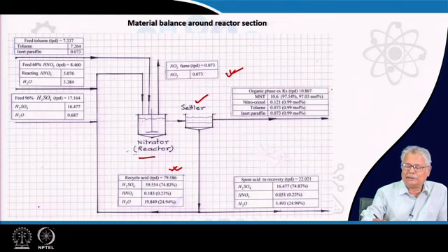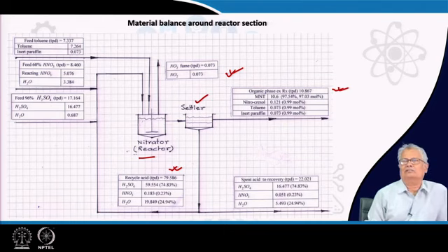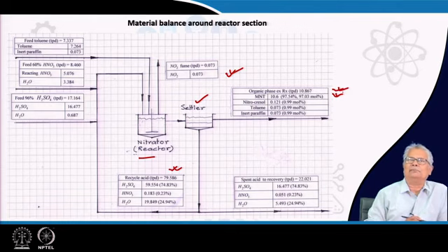Your organic flow rate will be about 10.867 tons. In fact, it has roughly around 10.6 of mononitrotoluene. The others are nitrocresol, unreacted toluene and a small quantity of inert paraffin which remains there. The entire thing is arrived at by calculations based on the conversion and the stoichiometric calculations.